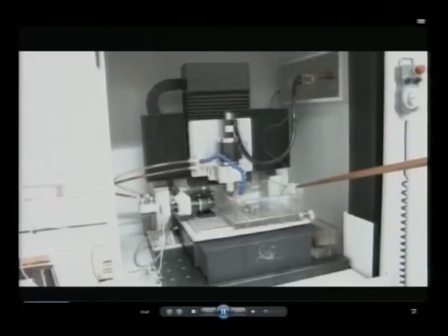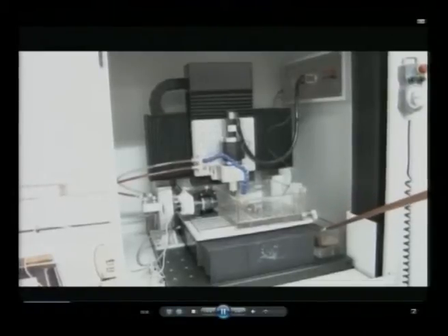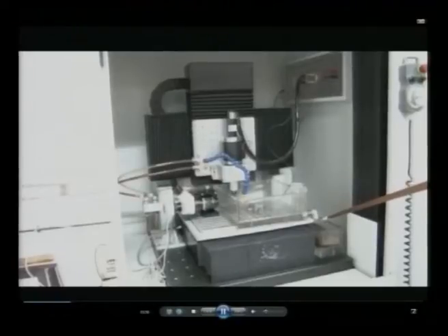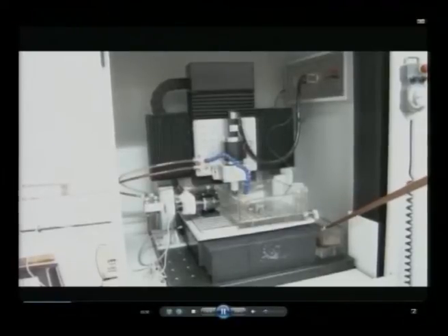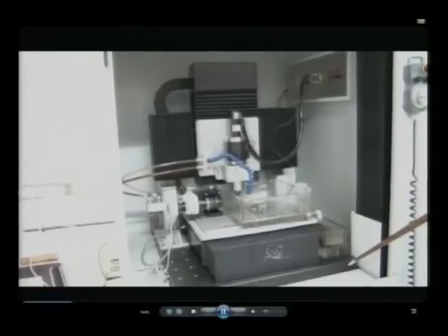Once the level is reached, the dielectric overflows through this valve to another tank which contains a filter. All the debris which is formed during the process is filtered in this filter, and the filtered dielectric will enter the tank which is under the table. In this way, the dielectric is recirculated continuously during the process, ensuring fresh dielectric for the process.